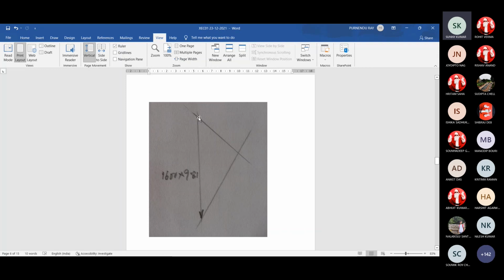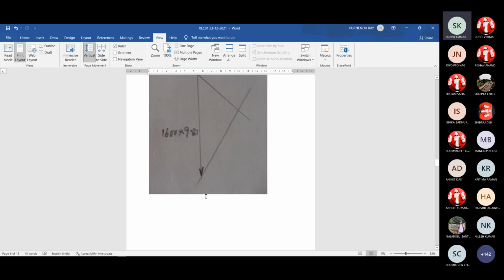So this simple thing, physically we can understand that this length is a little greater than this length. So the force in the member CB will be more than the force in the member CA. But we do not know really which value they have. Only thing, when we convert from this scale, that this 8 centimeter length represents 16 kilonewton force, then multiplying with that same scale, measured in centimeter, multiplied with 2 kilonewtons for each centimeter, we get these forces. Okay.